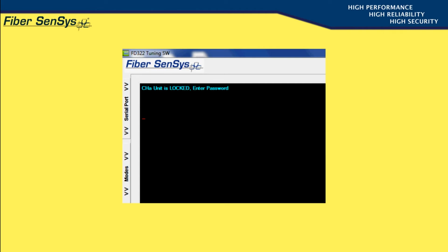The admin mode allows setting of several important system parameters. After typing in admin and enter, the first parameter displayed allows control of the tamper input function. It can be enabled or disabled here. Next, the alarm relay time, which determines how long the relays remain in the alarm state after an intrusion has been detected, can be set. The range is from 1 to 10 seconds, depending upon the requirements of your alarm monitoring system.